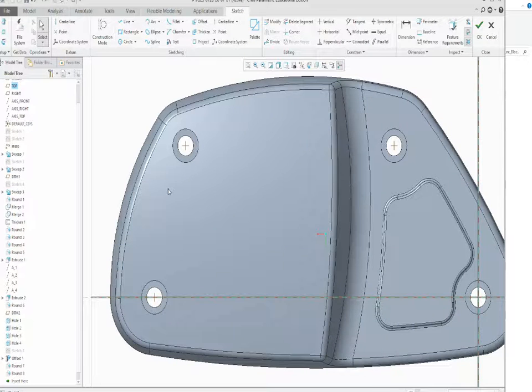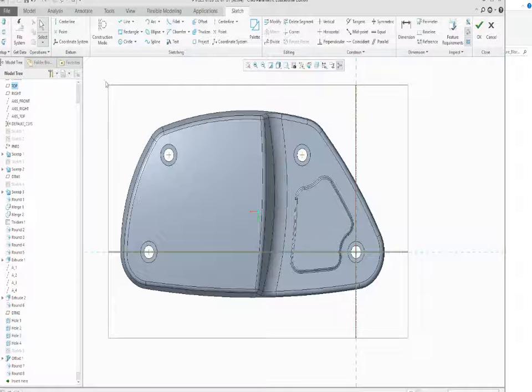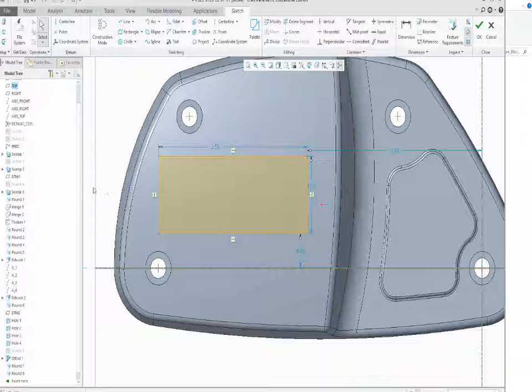Once we've got that, now we'll build for the name tag location on the design. I want to use a rectangle. And that's the outer location of the thing. I'm going to hit escape once and I'm going to stretch it, put it kind of centered. So that to me looks good for the design. So now I'm going to run fillets.